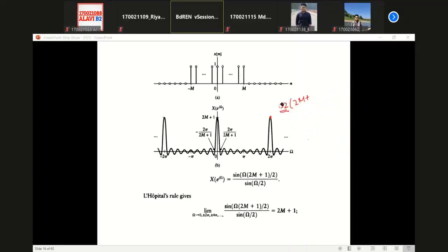But that will have a bandwidth requirement. We know that the magnitude of X(e^j omega) squared is also a measure of energy. If it is a measure of energy, then you can easily see that as this is the main lobe, your main lobe has a larger area than your side lobes. Your side lobes are diminishing. As a result, most of the energy is contained where? In the main lobe, isn't it?